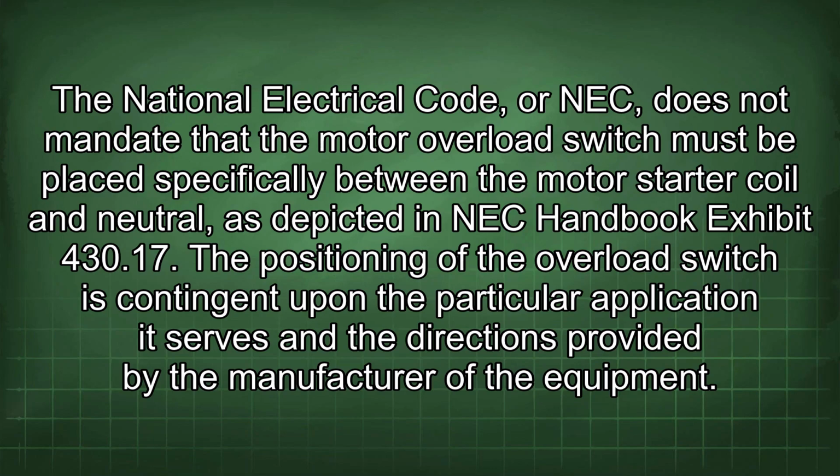The National Electrical Code, or NEC, does not mandate that the motor overload switch must be placed specifically between the motor starter coil and neutral, as depicted in NEC Handbook Exhibit 430.17. The positioning of the overload switch is contingent upon the particular application it serves and the directions provided by the manufacturer of the equipment.